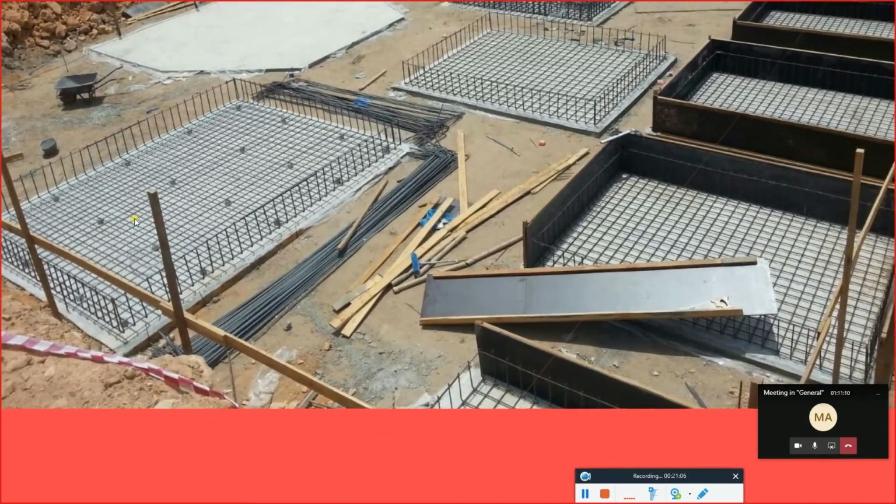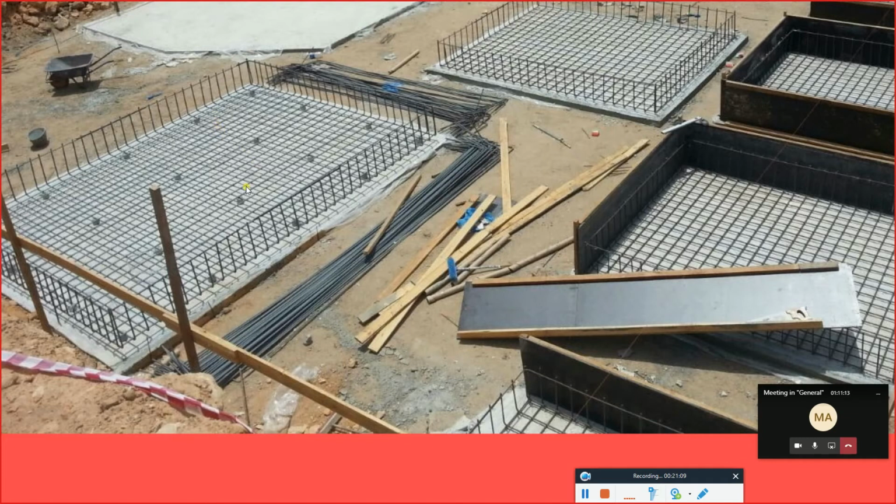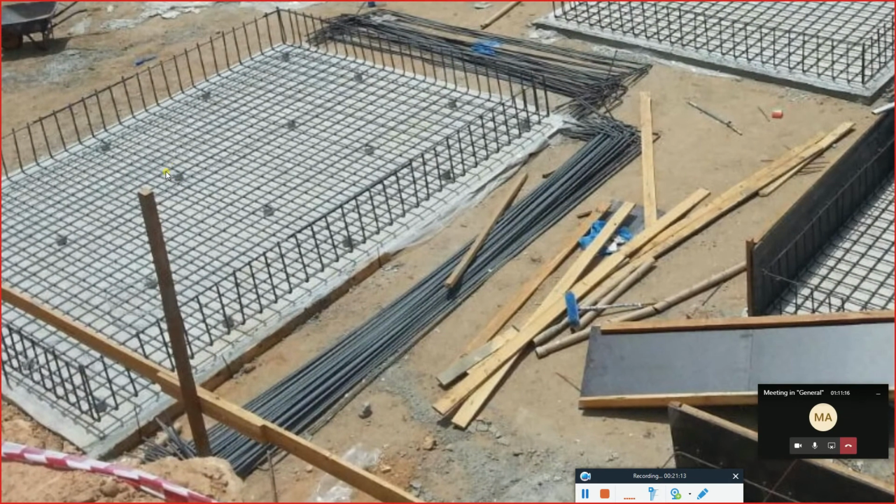Now here, if you look at this picture, we have covers. These small concrete blocks are acting as covers, what we call bottom covers, so that they ensure the steel will not be at the last edge. Why? To give the steel protection from moisture. So we keep a small concrete cover, and then we put the steel on top. Later on, this area is going to be filled with concrete.